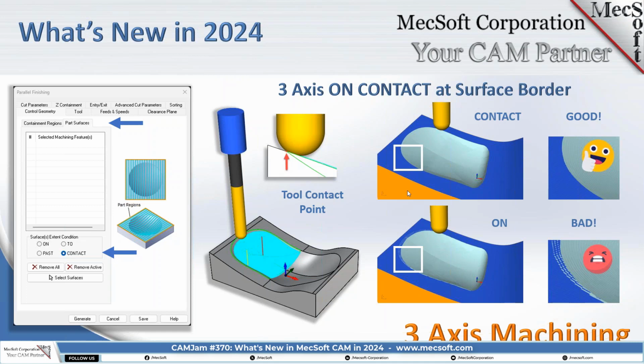If you move over to the next column over here, just by doing a cut material simulation, you can get an idea of how your parting line can be sacrificed. If you have been designing or cutting molds for any length of time, you know that the parting line is the sacred cow. You cannot violate it.